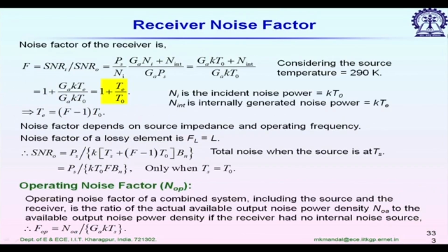Next, noise factor. Total noise contribution can be calculated in terms of noise temperature. Also, sometimes another parameter is used to quantify the noise contribution, called noise figure. We can calculate it for any given two port device. Usually, if it is a lossy device with some insertion loss, let us say L in dB, then the noise figure in dB simply becomes equal to L.